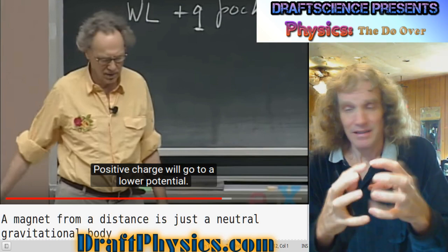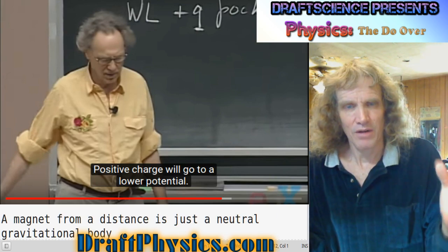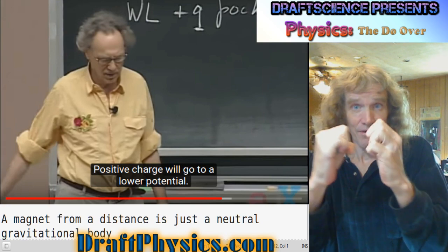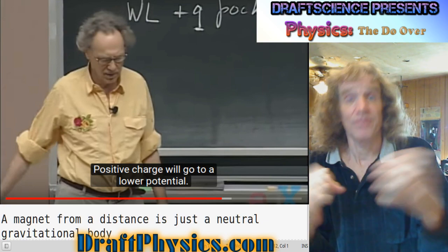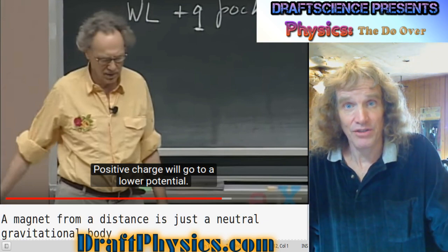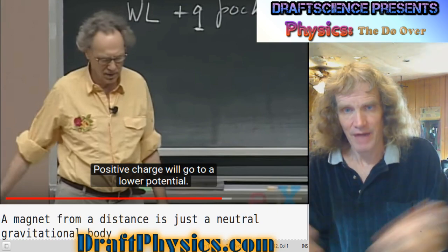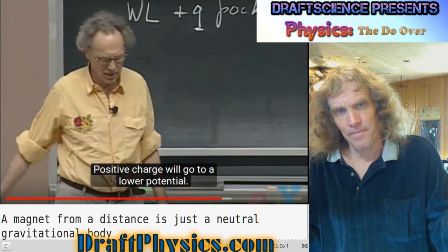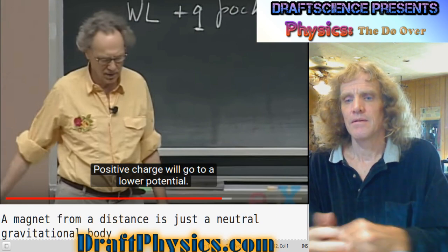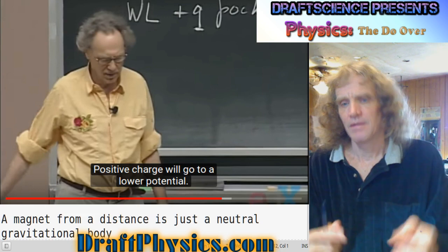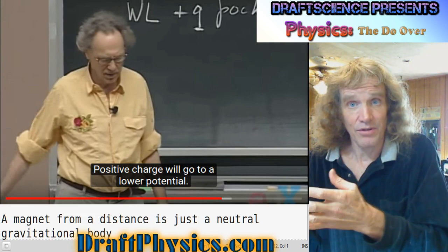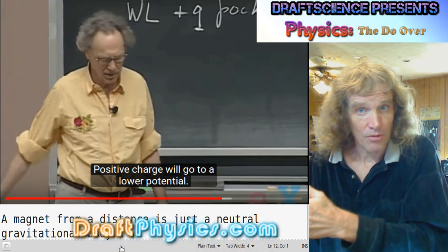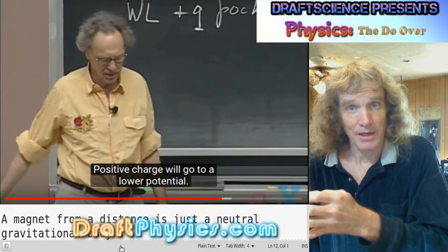And so once you compress it, it's compressed. It doesn't necessarily want to do anything. And the key is, as soon as it bangs into another atom, it's going to lose its compression, and it's going to share it with that other atom, and the pressure is going to exchange. And again, the real point is, I think, that what makes it look like the high pressure wants to go somewhere is the fact that the high pressure has more interactions than the low pressure. So it dominates.